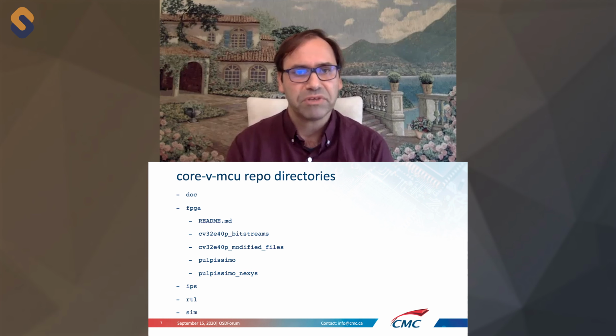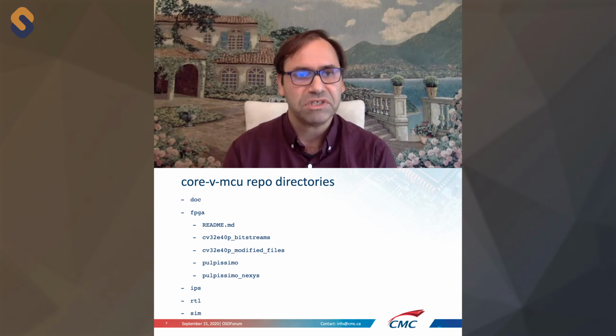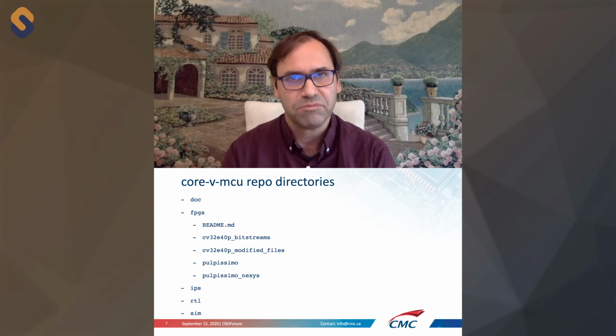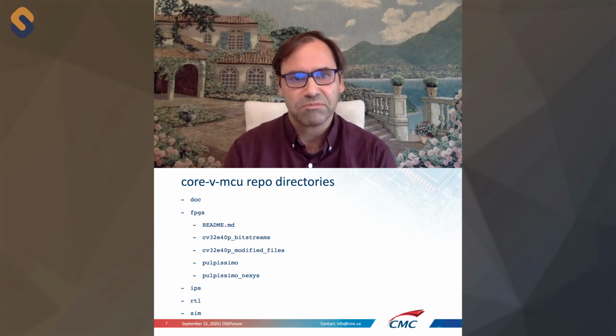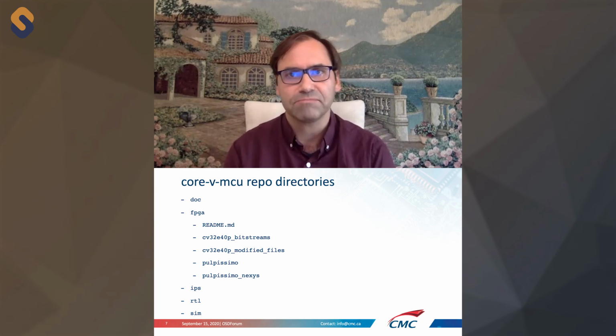There are pre-built bit streams for the CV32E40P platform in the subdirectory there, as well as the Pulpissimo platform, which gives the top-level RTL for the FPGA platform. And then there are several directories for the specific FPGA boards that are supported, including the Pulpissimo Nexus board.